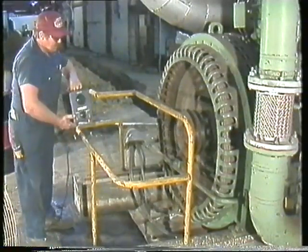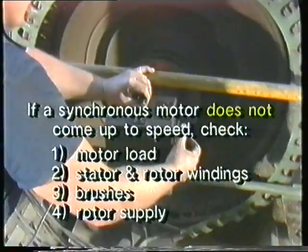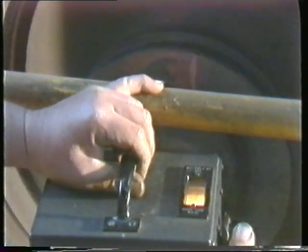If you find a synchronous motor running below synchronous speed, the motor may be overloaded. The stator windings, rotor windings, brushes, or rotor supply may be bad. If the problem continues, the motor will burn out.